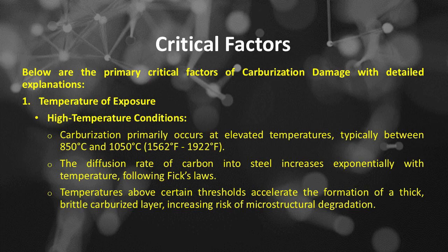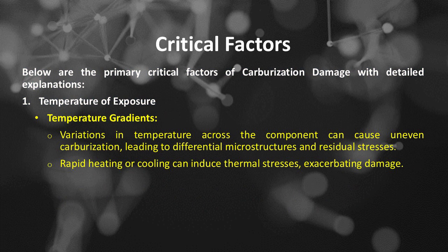The diffusion rate of carbon into steel increases exponentially with temperature. Following Fick's laws, temperatures above certain thresholds accelerate the formation of a thick, brittle carburized layer, increasing risk of microstructural degradation. Temperature gradients, variations in temperature across the component, can cause uneven carburization, leading to differential microstructures and residual stresses. Rapid heating or cooling can induce thermal stresses, exacerbating damage.